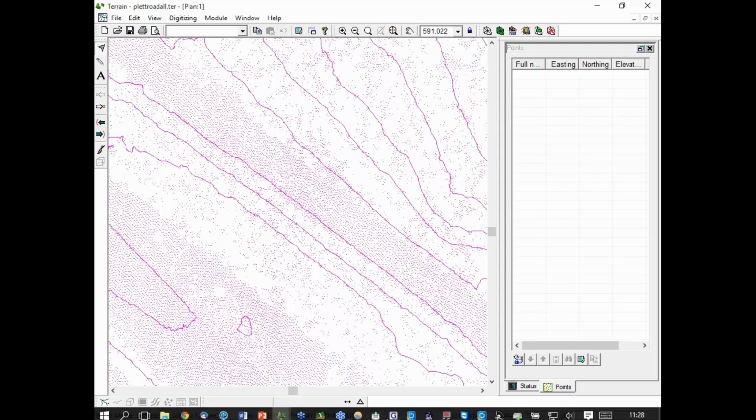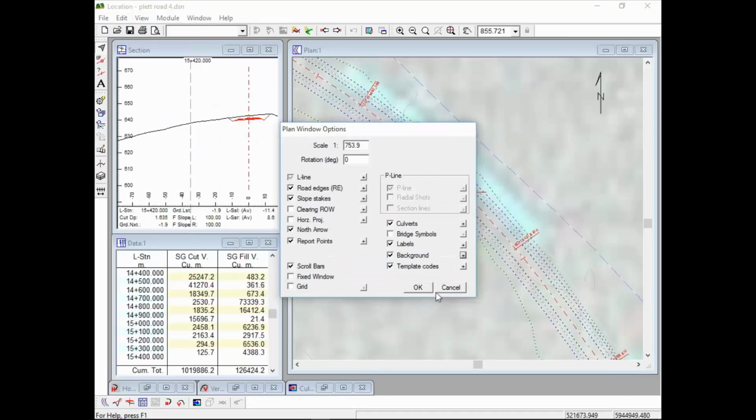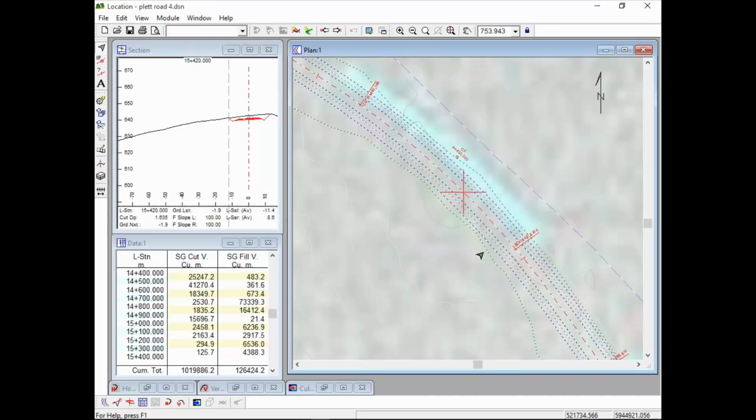are thick. Right. So an interesting workflow in location is to actually do a preliminary design on a thinned LiDAR surface. So it's basically going anywhere you want, and then resample the LiDAR or reread it so that it's dense in the area of interest in your corridor.